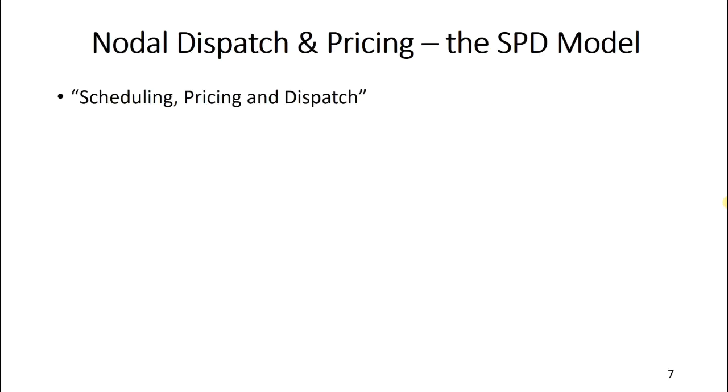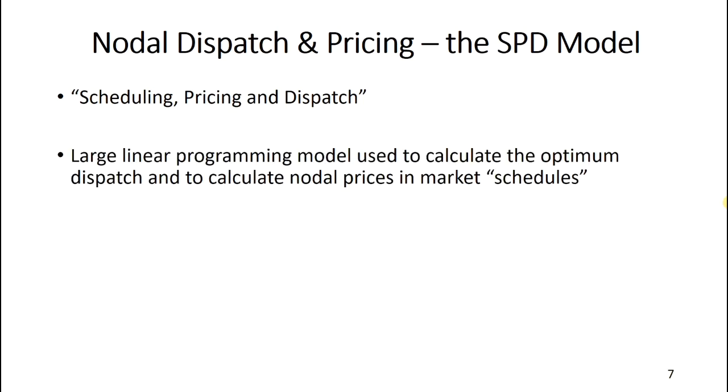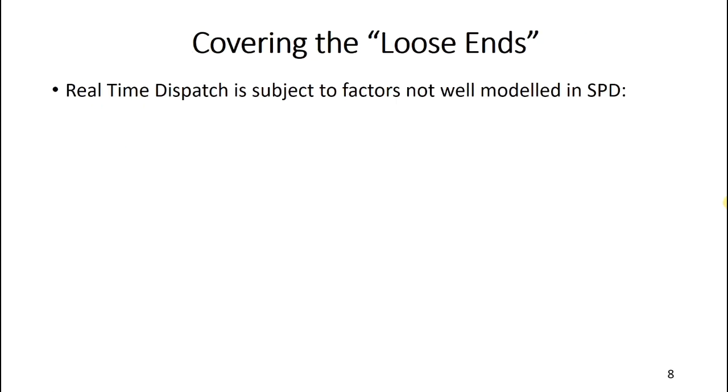And when we talk about nodal dispatch and pricing, we're really talking about the SPD model. SPD stands for Scheduling, Pricing and Dispatch, and it's a very large linear programming model used to calculate the optimum dispatch and to calculate nodal prices in what's known as market schedules. But there's some loose ends that we have to cover off, and this is because real-time dispatch is subject to factors not well modelled in a linear model such as SPD.